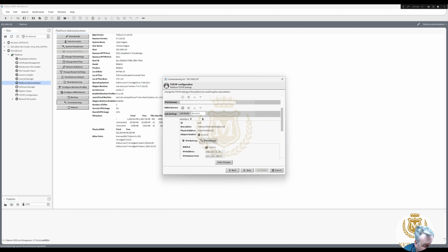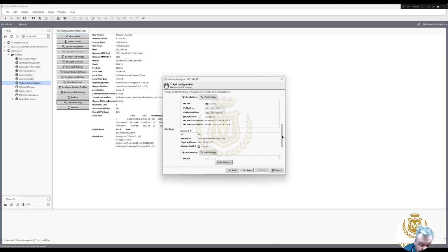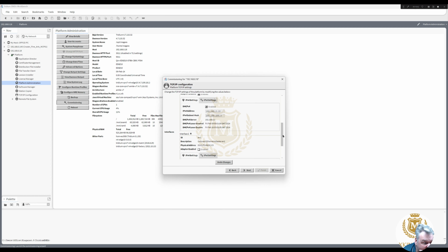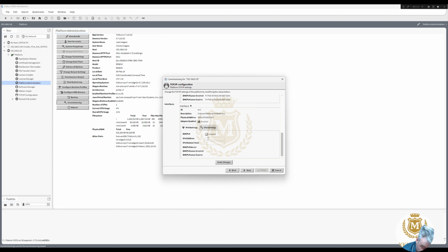Tell you what, I am going to do a standard. Because it's using a router, I really need a fixed IP address. I don't want it to tell me what address it is. So I'll take that out of there, and I'm just going to use 1.140, which is a basic address for a Jace 8000. And then I'll enable this adapter: 10.0.0.125, 255.255.255.0. So now I'm in command of the IP addresses and those sockets, so I know what they are.